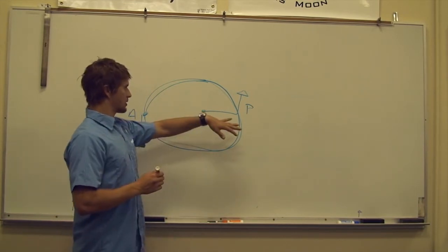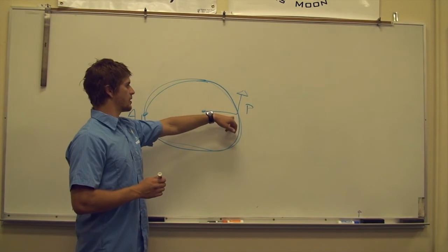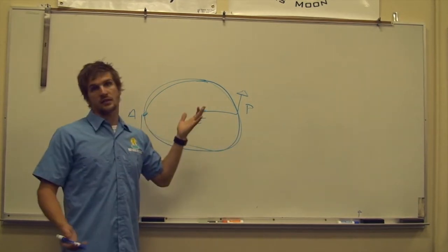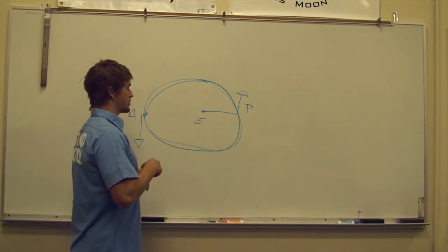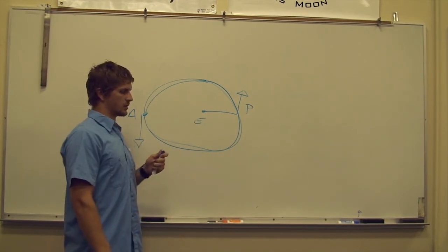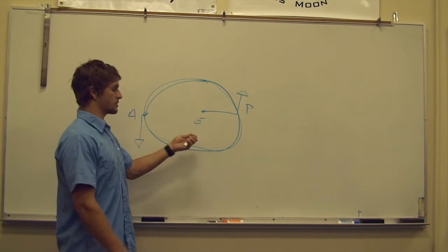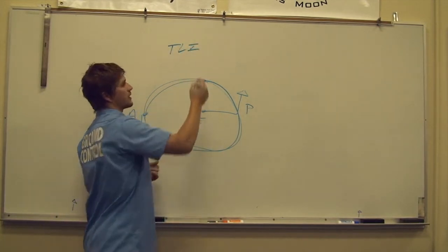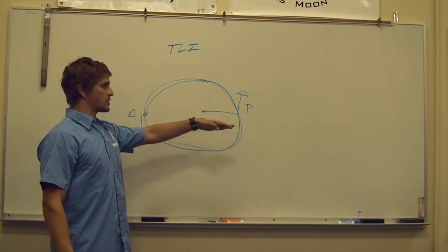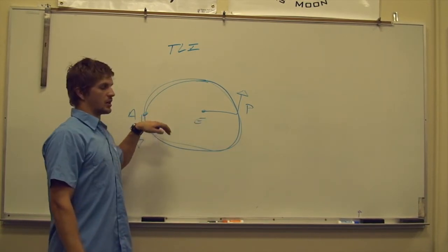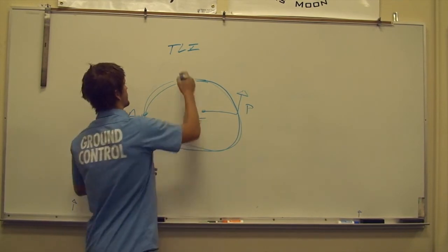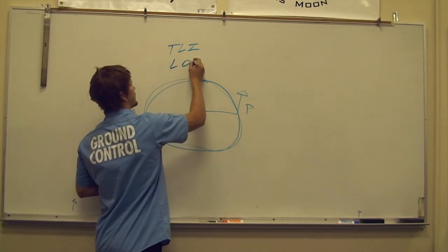Essentially, we are looking at an average launch time from the Earth over here to the moon of about 5 days. To shorten that time, you're looking at doing an accelerated burn through your translunar injection, also denoted TLI, in which case you will undercut the moon and you will have to do what is called a lunar orbit insertion to capture the moon, which is denoted as LOI.